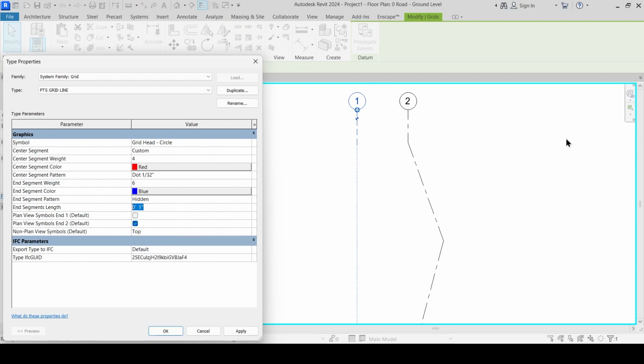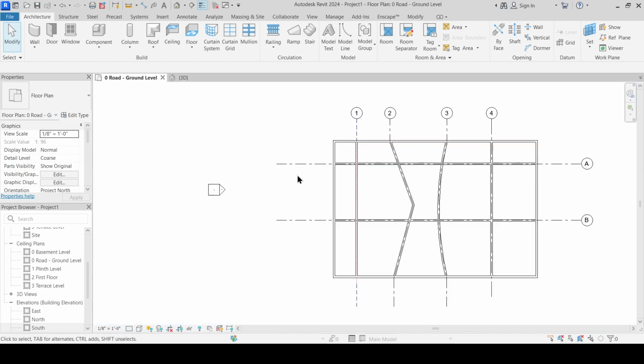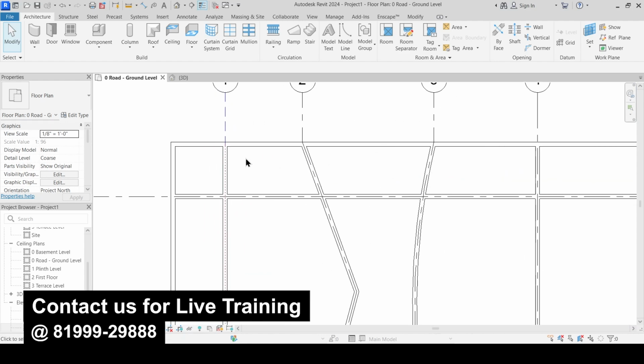So depending upon the wall, let's say HR, if you just click this eyeglasses, then you remember that we have temporarily isolated these two lines. If I just press HR, that is the shortcut, it will unhide it. Okay, fine.